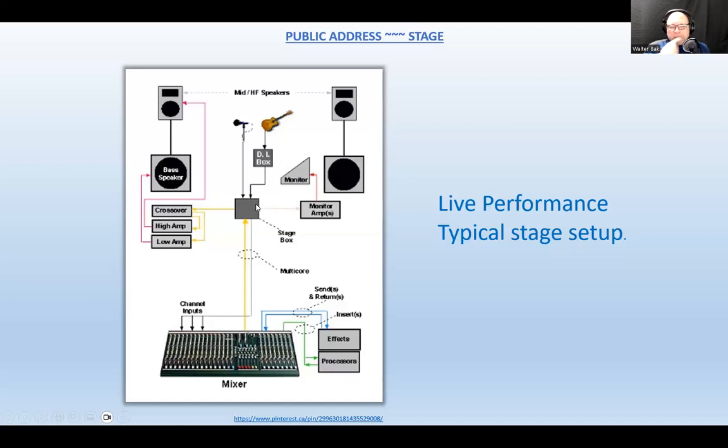So for that reason, the signal is being returned from the output of the mixing board, and that signal will have maybe 600 ohms, 800 ohms, 300 ohms, whatever it is specified for. It's going to travel through that wire and it's going to be plugged into the amplifier, and the amplifier output, which is 4 ohms if it's a high-powered system, then the cable that joins the amplifier and the speaker is not going to have as much resistance if it's 20 feet long as if it were 100 feet long.